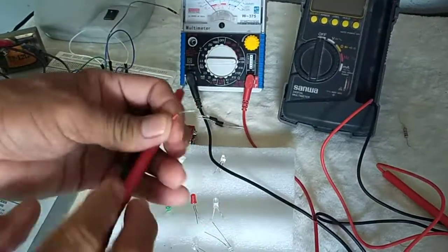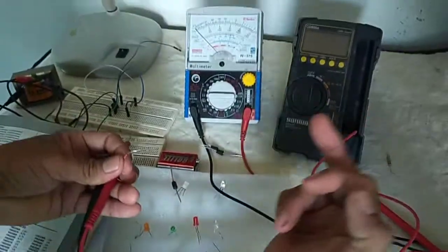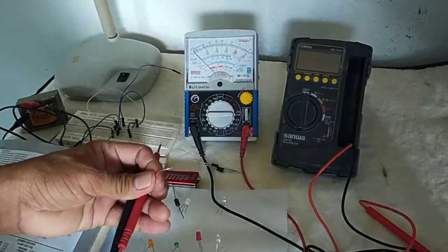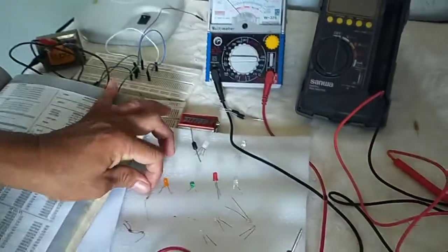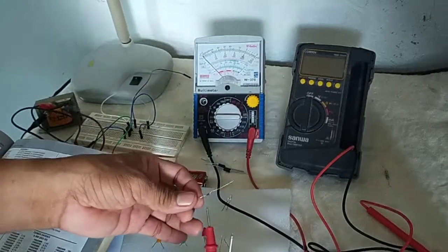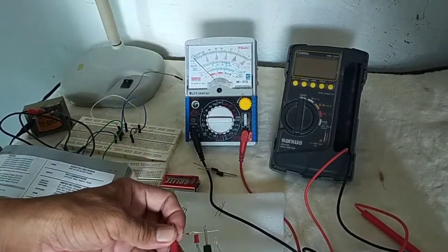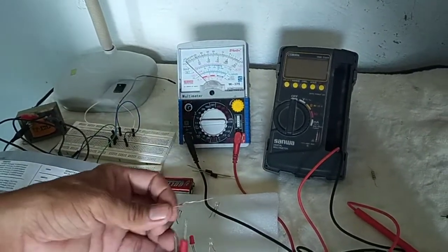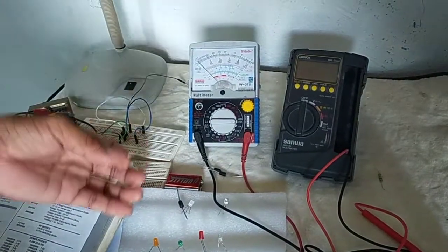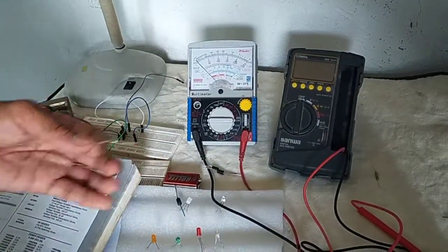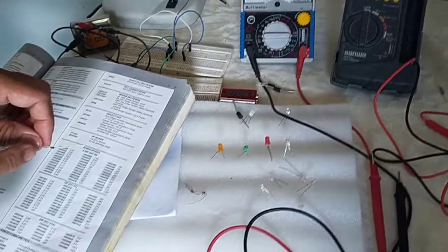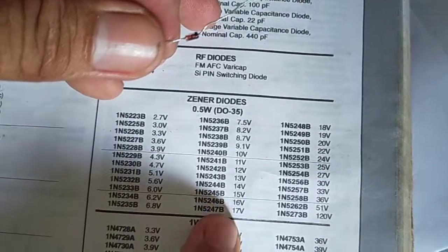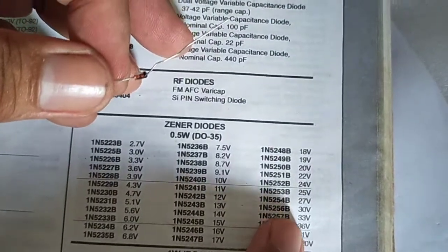No? The higher the deflection in the reverse direction, the lower the reverse breakdown voltage or the Zener voltage. But here, very high voltage, 27 volts. There is no more deflection of the pointer in the reverse direction because the Zener voltage is higher, around 27 volts. We can see that one. For example, this is 0.5 watt or 1/2 watt, and this is 27 volts. 27 volts we have here, here, here, here.